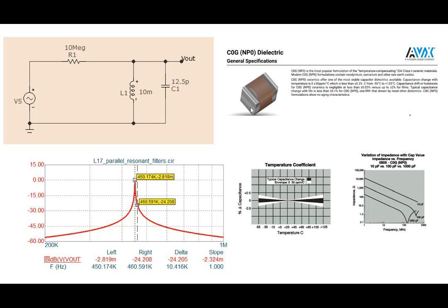So at some higher frequencies, omega L, the little bit of inductance in your capacitor leads, starts to become important, and you start getting distortion here. So all of your components, whether you pick up a resistor or a capacitor or an inductor, would fail at certain frequencies. They would not act like the inductance that you want or the capacitance that you want.